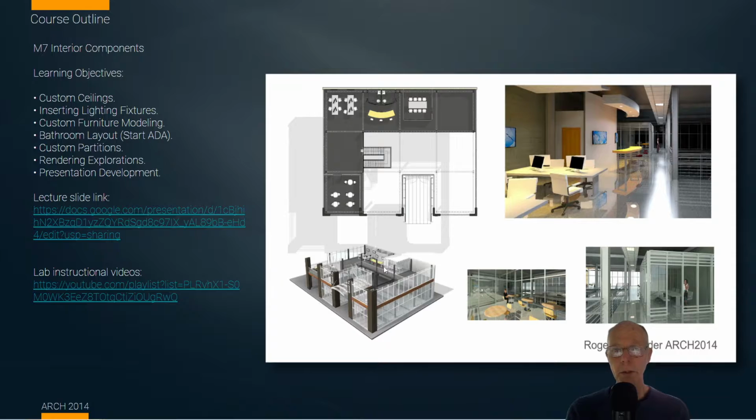We then go back into the building that we've been working on, that commercial building, and start looking at creating interior detailing. We spend a lot of time creating bespoke components. The countertop here is completely fabricated. The desktops are Revit family models that we create. The actual monitors that sit on the table are custom created. We look at the idea of ceiling clouds and creating different kinds of shapes and lighting systems to be placed in them. And we get an introduction to ray traced rendering inside the Revit environment.